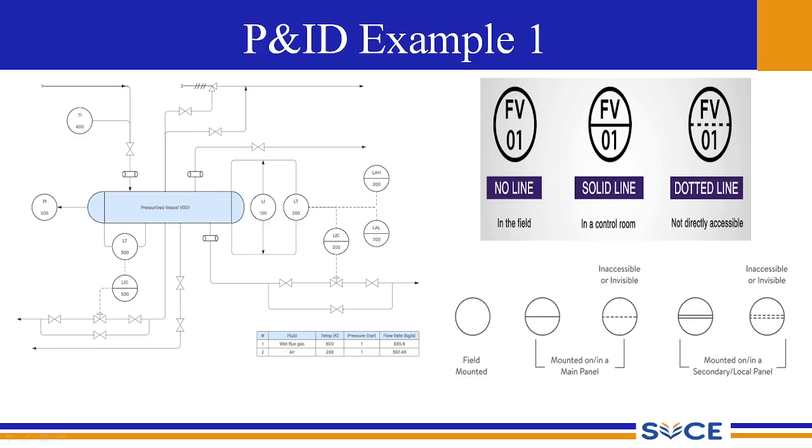There should be a feedback loop to regulate the level, using level indicating controllers. Whenever this pressure vessel is released to drain the fluid or to fill the vessel, we have to look at this control loop for measuring the level of the fluid inside the vessel. This control loop is indicated by this LIC, that is the level indicating controller. The level indicating controller gets the signals from the level transmitter, and the pressure of this pressurized vessel is indicated in this PI.